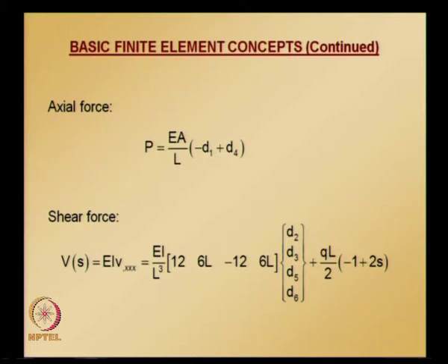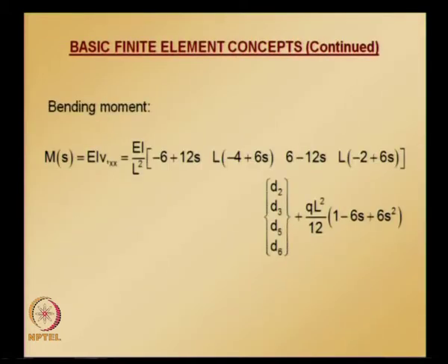And similarly we can also calculate bending moment, where we also need to apply fixed end solution correction. So this is the procedure for solving frame problems.